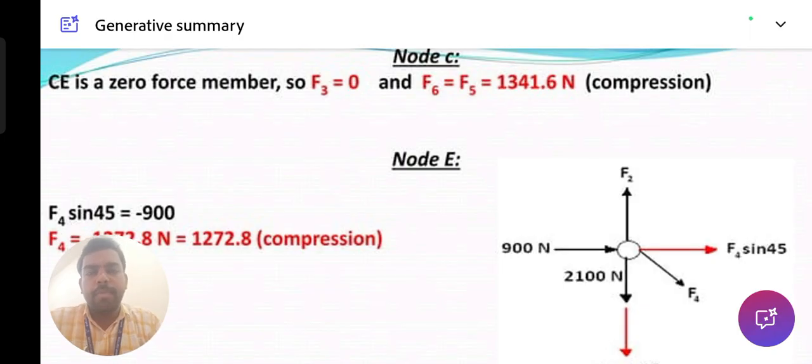And that is important in this unit, purlin design is also very important. In that purlin design it should be capable of carrying the whole vertical loads acting on that particular truss. So that is very important to design. Okay, these are the trusses and types of trusses, what forces act on them, and how to find out the loads, moments, and reactions on the particular truss.